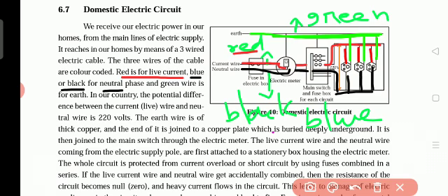When we put the plug in the socket in the house, there are three holes. To one hole the red wire is connected, to another hole the blue wire is connected, and the third hole will be big in the plug. This third hole is connected to the green wire, and the green wire is connected to the earth. Understand? At the plug point, down are two small holes, and on top is the big hole.